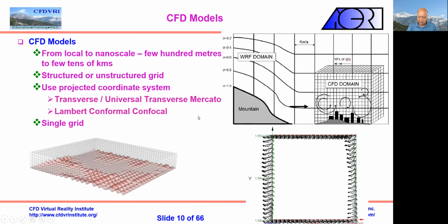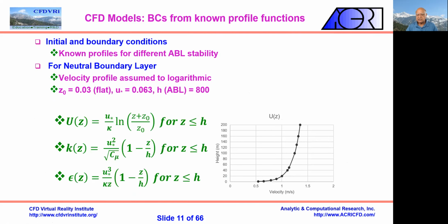this model, okay? Now, one more thing you do is that CFD models cannot go right down to the ground. There is a boundary layer, right? You remember from my turbulence lecture that with walls, you don't go down to the wall because you need a very fine grid. There's a high gradient, same thing happens on the ground. So this profile is typically logarithmic. As we said, it's no different than any other wall. And so what we do typically in these models is that we put in the values of kinetic energy, U and epsilon, etc., from these relations, okay? And so that is what drives the model in the atmospheric boundary layer, the ABL, as it's called here.